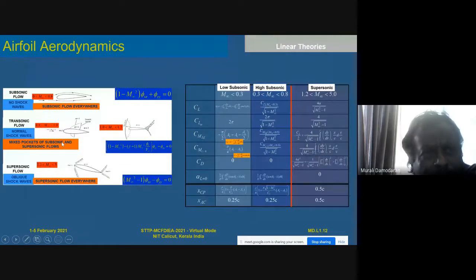So the small disturbance equation, you can simplify it between Mach 0 and 0.8. I basically get a simpler equation like this, which is elliptic in nature. And for supersonic flow in this regime, some of the terms can be dropped out, and I will get this one. These are simple models, and these are linear, the supersonic and subsonic flows, and you can get very elegant and quick estimates for an airfoil. So these are estimations based on linear theories, high subsonic and low subsonic. This is what an aerodynamics student will probably learn in school.